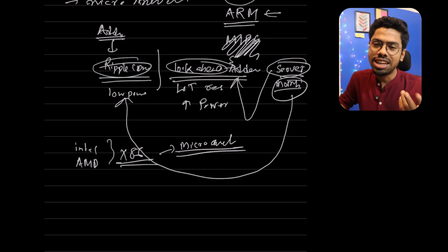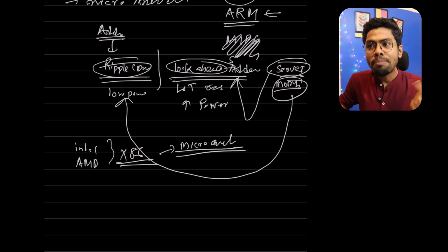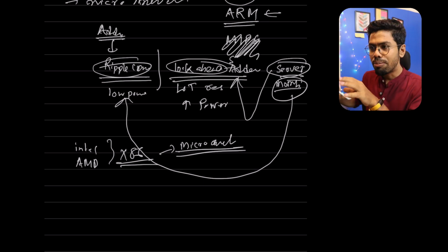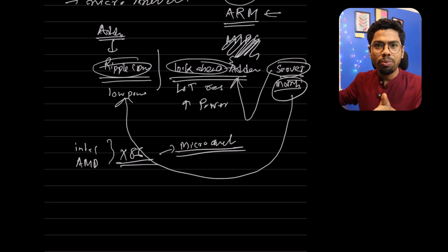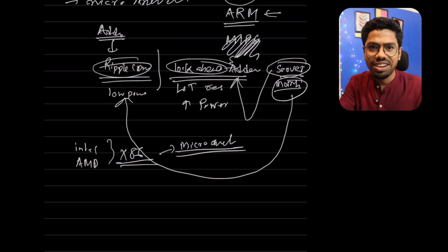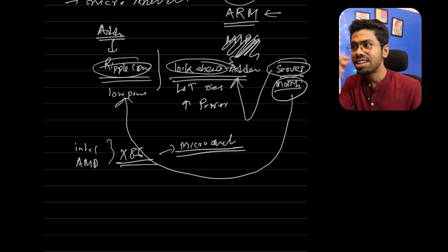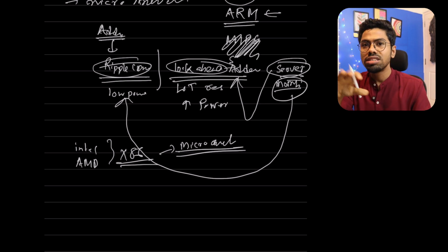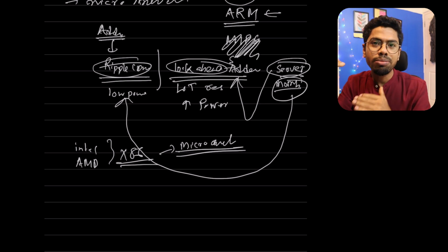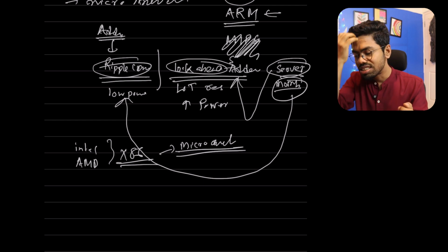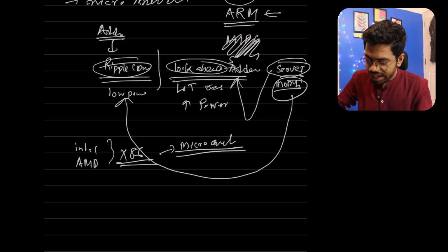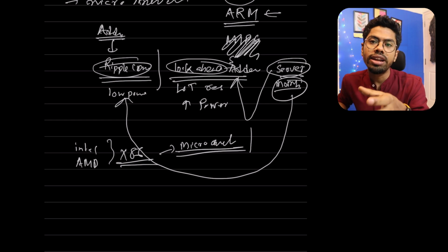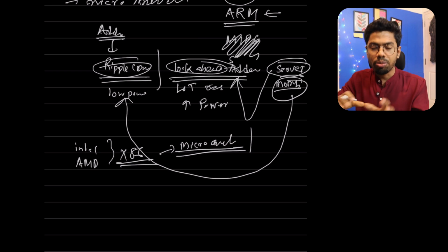So x86 is designed by two companies, but they might have their own proprietary idea of how to arrange those particular registers or IO pins or other things, right? One may decide that we will have 32 general purpose registers. Other might say no, we need 64 general purpose registers, and that will bring rise to your microarchitecture definitions. Now you might be a little confused about architecture and microarchitecture. Architecture is defined by the instructions your processor will follow.